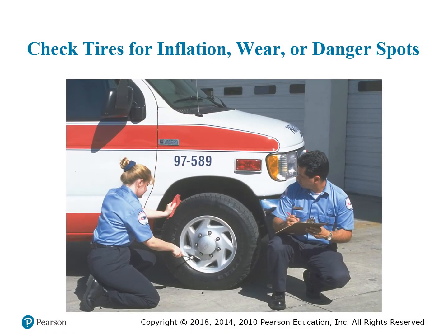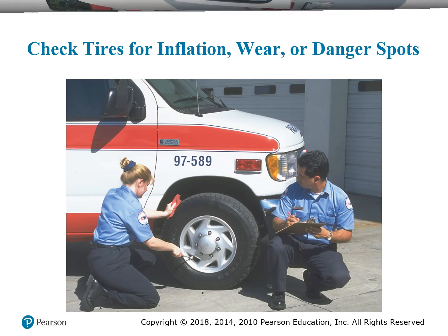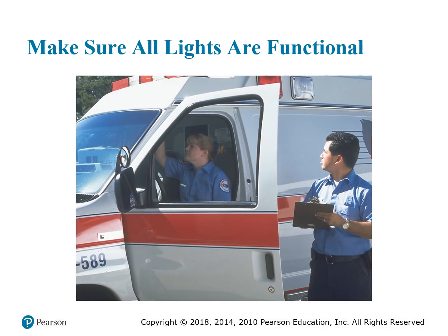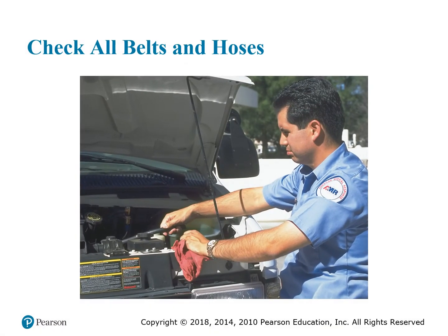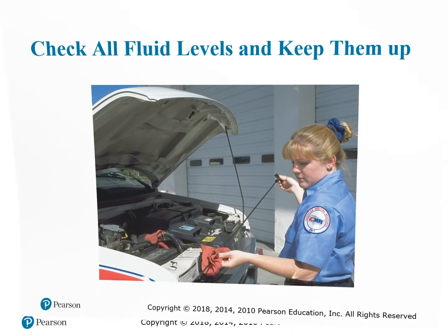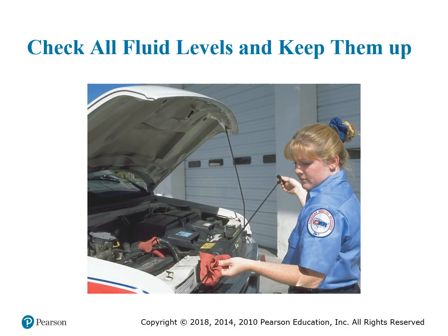Check tires for inflation, wear, or danger spots. Make sure all lights are functional. Check all belts and hoses inside the engine compartment. Check all fluid levels and keep them up.